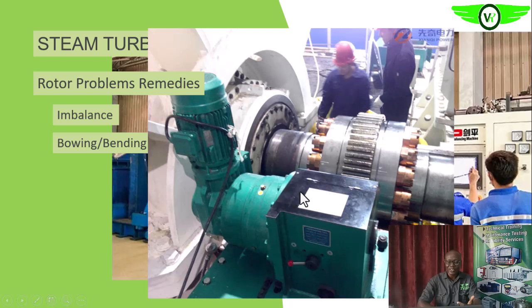So during startup, as we are administering steam, the equipment has not actually started turning. As we are administering steam to heat up the turbine, we will start the turning gear to be turning the rotor at that very low speed to help us to evenly heat the rotor.